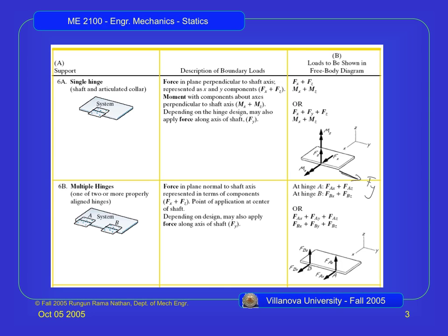So here's a hinge, this is really what we got over there. I had two hinges on the actual system itself, so this is the diagram over there. Now, in this diagram, there's no moments shown at all. The reason they're not shown is because as soon as you have two forces fixed in these directions, it automatically means that it cannot rotate in those other directions. Remember how you would be given a physics problem and sometimes you were given a little extra information? You didn't really use it in the problem? It's extraneous. You don't need to show that because these are fixed in both spots. If it's fixed here and here, how is it possible to rotate? It can't. When it's only fixed here though, you need to show that it can't rotate with the actual symbol.